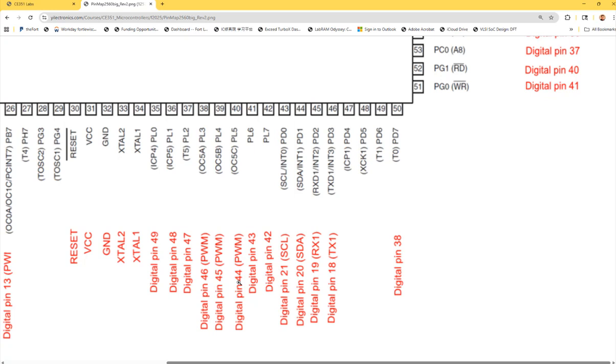Question number 19. When we change RX1 to this baud rate, would it affect the baud rate of 9600 bits? Why? That's a really simple question. So it doesn't, because the 9600 bits is set up from the Serial.begin(9600). That's for UART0, right? There's nothing to do with UART1. There are two different UART modules.